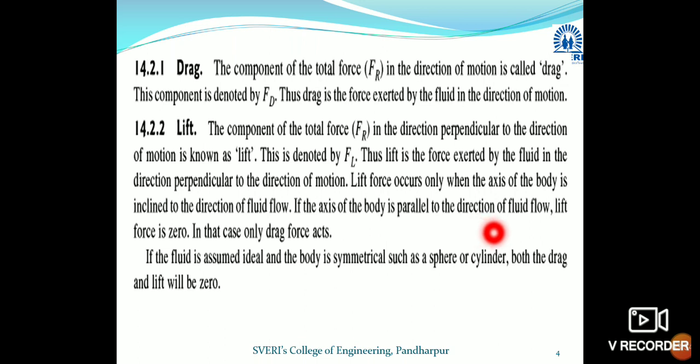So lift force occurs only when the axis of the body is inclined to the direction of fluid flow. If the axis of the body is parallel to the direction of flow, then the lift force exerted on that body will always be zero. So to have a lift force acting on that particular object, the requirement is that the axis of that body should be inclined to the direction of flow. Then and only then will a lift component be exerted. Otherwise, if the direction is parallel, the lift force will be zero.